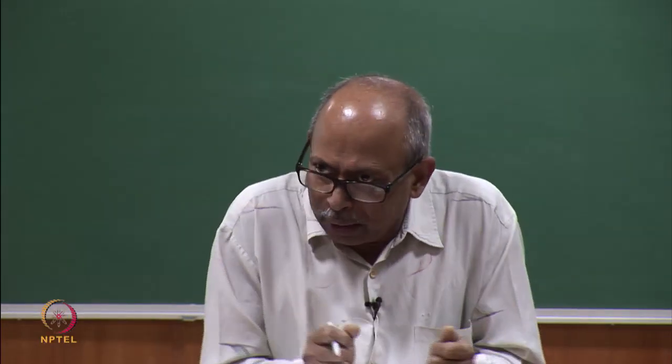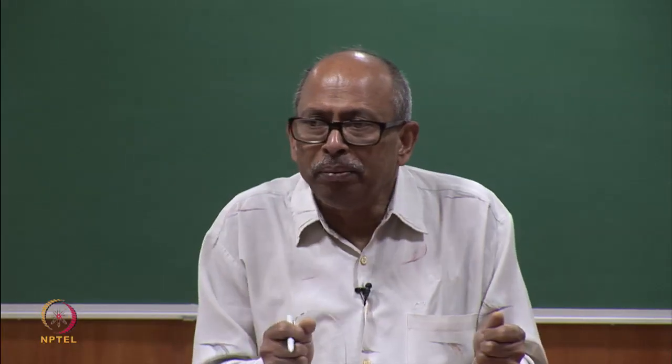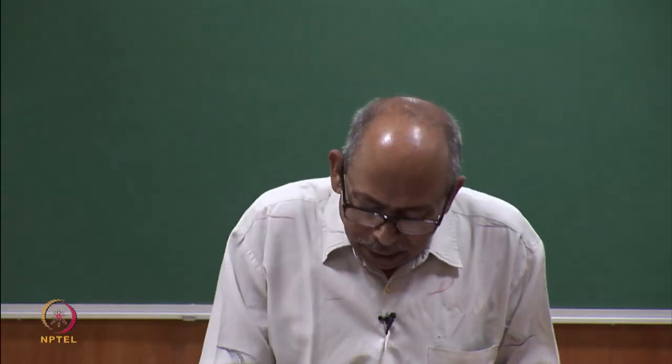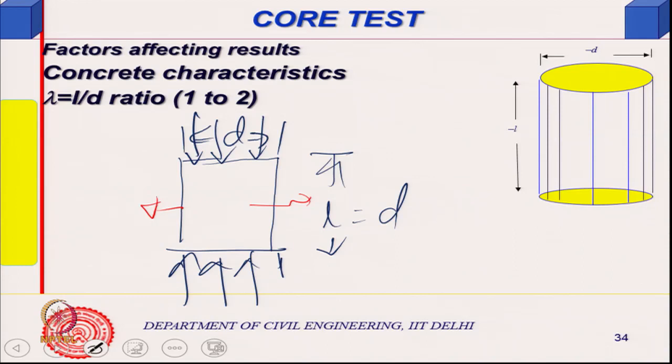You can push them, they can withstand a lot of load, but if you try to pull them, they separate out. So, the load carrying capacity or strength along this direction is much less in tension compared to this. So, you will have cracks of this kind in cube or cylinder failure.